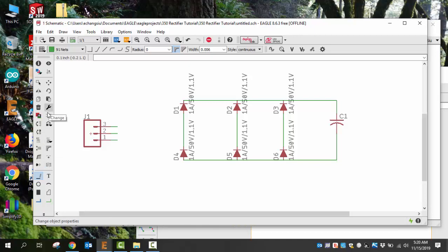So let's see, where's the label command? Label. There it is. If I click this extra down arrow, I go up here carefully, add label. And so you can see that these are wired as N$6, N$7, N$8, and I'm going to go over here and label this one and this one. And I want to connect this N$1 to N$6 and 2 to 7 and 3 to 8.